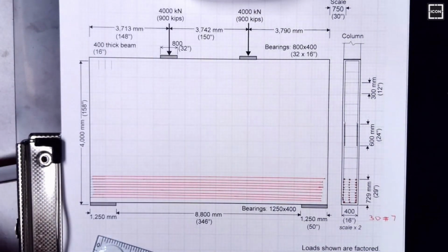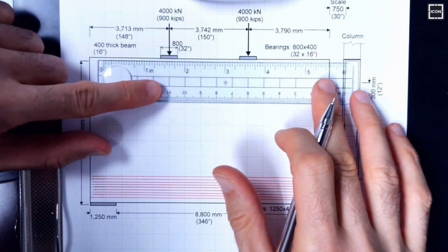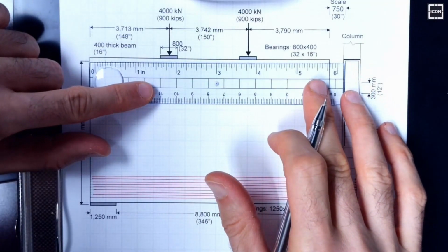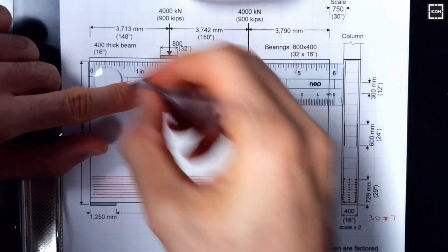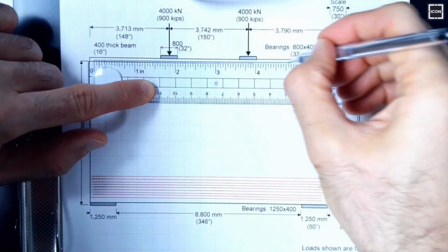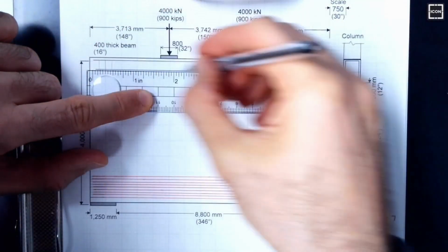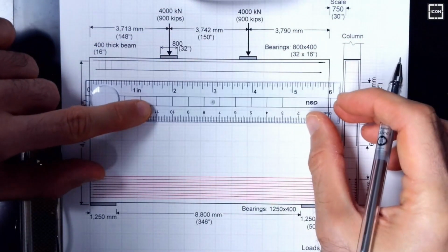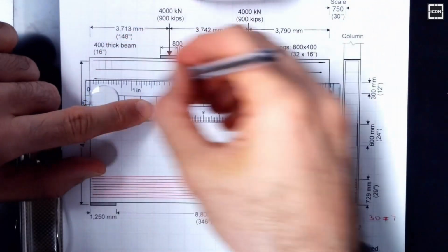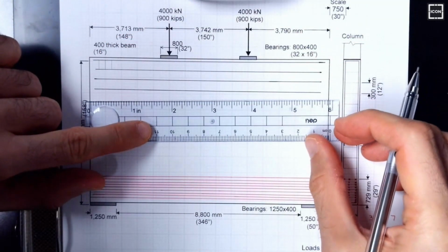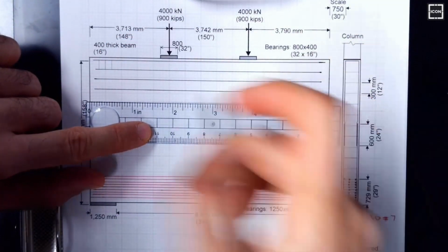I'm just going to be putting crack control reinforcement. Of course, you want to put one at the clear cover location. I mean, as if you are putting a main reinforcement. So it is here. The second one, you can see all these lines. They correspond to crack control. I mean, it's pretty significant crack control reinforcement.